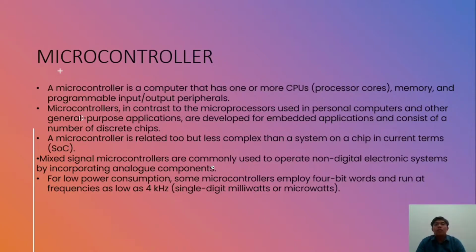The microcontroller is related to but less complex than a system on a chip, which we call an SoC. Mixed signal microcontrollers are commonly used to operate non-digital electronic systems by incorporating analog components. For low consumption, some microcontrollers employ 4-bit words and run at frequencies as low as 4 kHz.